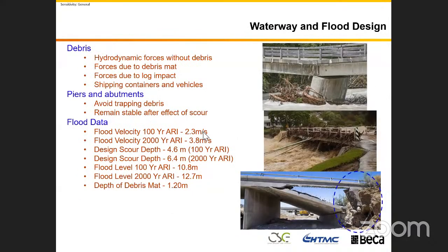Sorry, I got late. Windsor Road Bridge. You know where it is. We just rehabilitated that one, and in the last flood, about 1 year back, it went underwater. I asked the engineer at the time what the return period was. She told me it was a 20-year return period. The argument was that RMS knew it was going to go underwater, and they purposely selected this 20-year because all the approach roads are going to go underwater in any case.